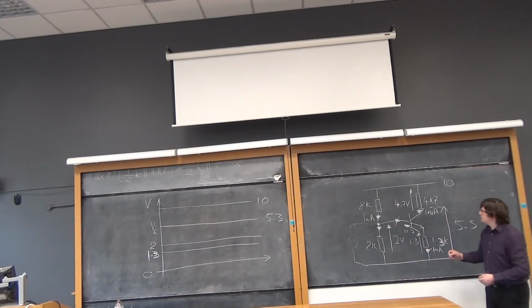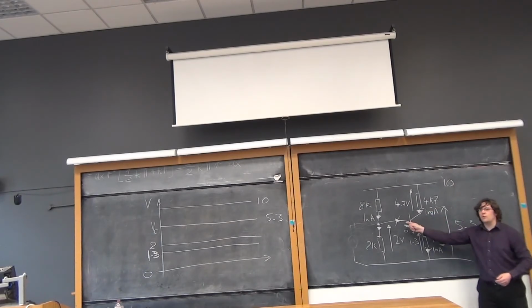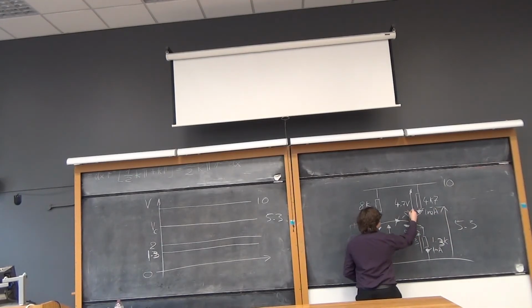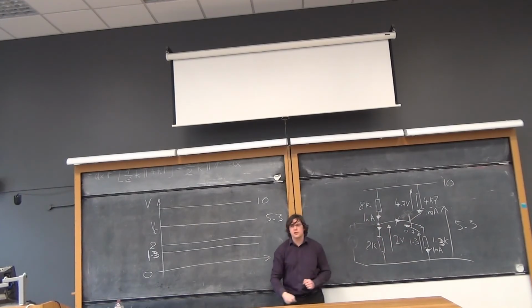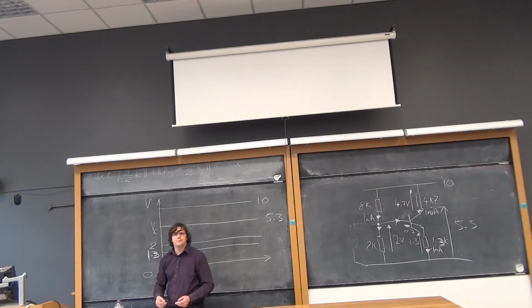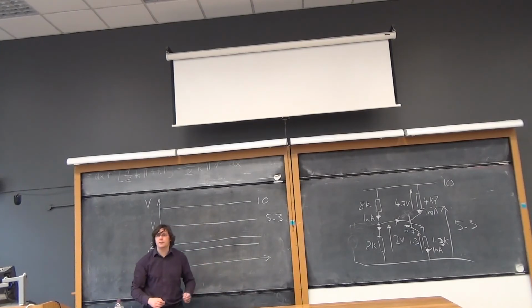And we can't have a situation where the collector voltage falls below the base, because if we do, the diode which is in here, there's a little diode that lives there, facing that way, it will become forward biased. If this voltage drops below that voltage, it will almost certainly switch on. And that means that our transistor will have 2 forward bias junctions, which will put it into switching mode or saturation. And that's no good, because we need an amplifier.